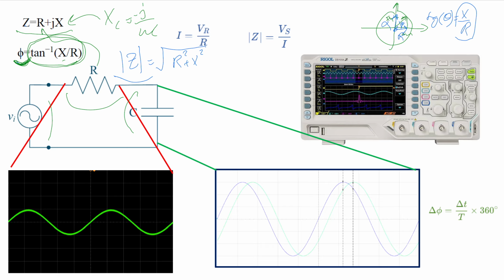Now you can have the amplitude of the Z. Now, how can you find the value of the voltage for the resistance and capacitance and the value of the current passing through those systems? For calculation, if you have the Z, you can simply say, I have a source and an impedance, which I already calculated the values. Now it's simply Ohm's law. It's a simple Ohm's law.